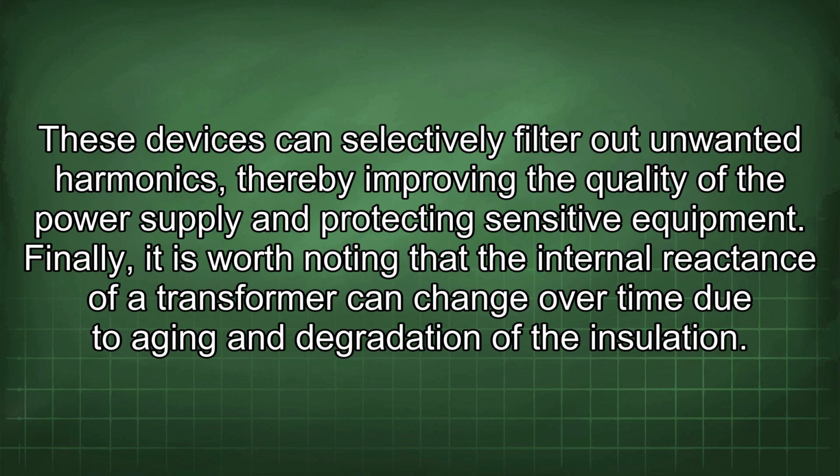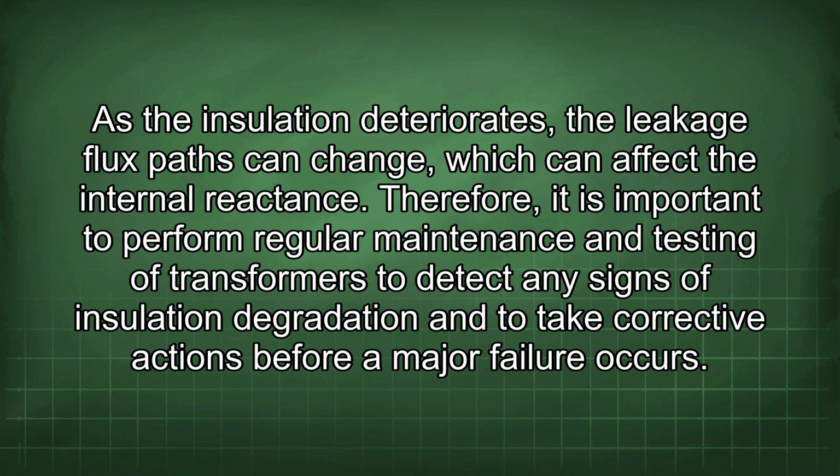Finally, it is worth noting that the internal reactance of a transformer can change over time due to aging and degradation of the insulation. As the insulation deteriorates, the leakage flux paths can change, which can affect the internal reactance. Therefore, it is important to perform regular maintenance and testing of transformers to detect any signs of insulation degradation and to take corrective actions before a major failure occurs.